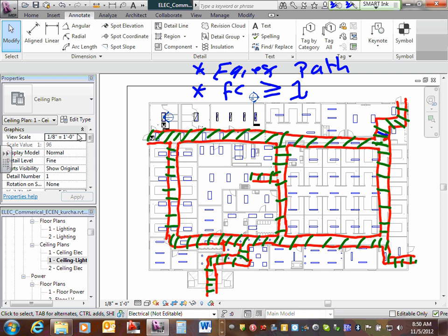Here's what we typically do. I don't do it optional, if you want to. You take this to visual and you do calculation. You place your fixtures, you do calculation. You place your fixtures here, you do a calculation and make sure you get an average of what? One foot candle. Okay. Who decides on that one? The architects and the engineers. When they get together, typically the architects decide the egress path.